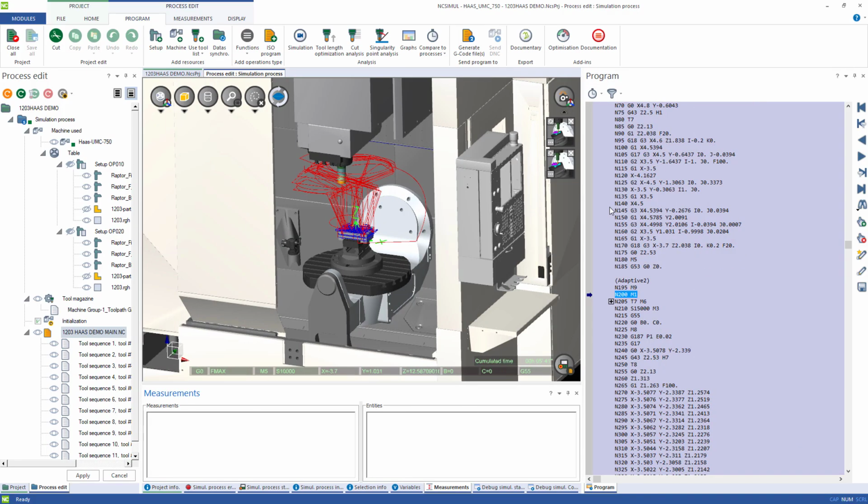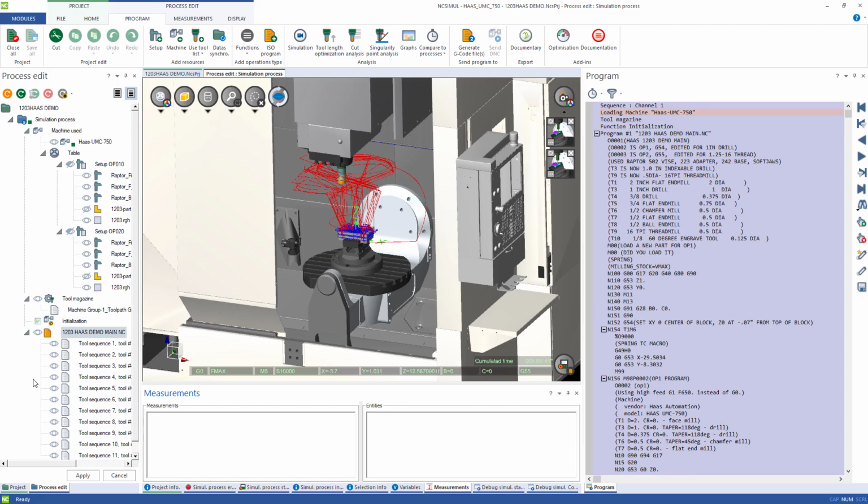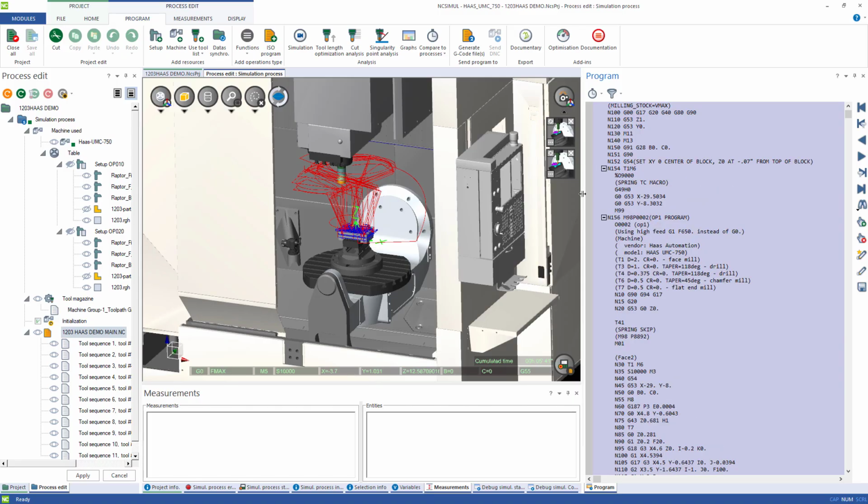On the right-hand side over here, we have what's called the program window. And again, it's that same post-process G code plus any of those subroutines or macros that we incorporated into the digital twin. So as I was saying, for example, we have a tool change macro for T1M6 that's pulled off your real-life machine, and I can just hit the plus sign to see the decomposed motion occurring in the background whenever the G code calls that.